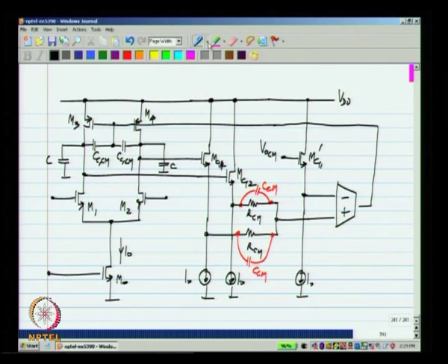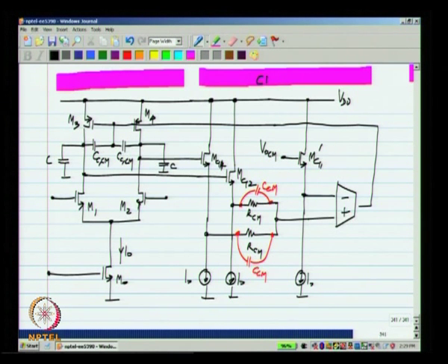Okay. So, now the circuit looks very complicated, but it is not. This part of it constitutes the fully differential single stage op amp, and M3 and M4 should act as constant current sources in differential mode. Now, the rest of it is for common mode feedback, and this part is for detecting the common mode, this is for the replica, and this is for feeding it back to the gates of M3 and M4, and these are for stabilizing the common mode, that is to make the loop gain of the common mode feedback loop look like an integrating function. Okay. And there are many parasitic poles here and also zeros.